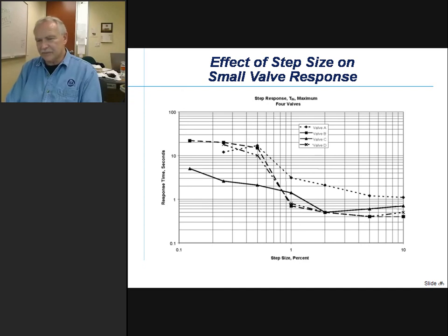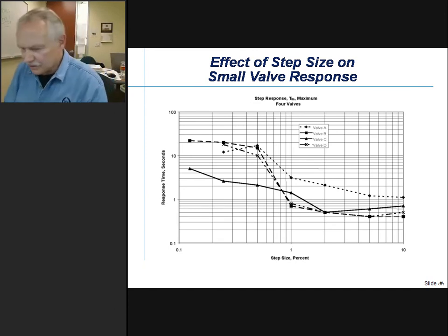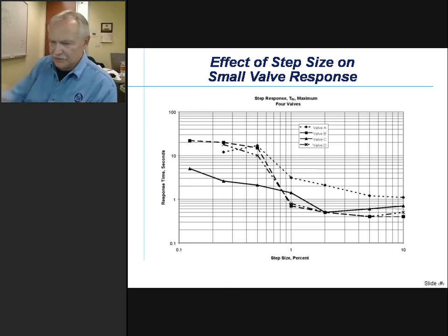Well, if you look at what's happening from one module execution to another, hopefully the output is not changing by 50%. If you have 50% changes in your output, almost any valve, even if it doesn't have a positioner, is going to respond. And maybe it's slower for the big valves, but you're not going to see really the effects of backlash and stiction, and in particular some other issues that arise in terms of sensitivity as determined by the actuator and positioner.